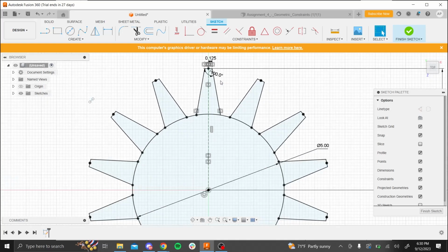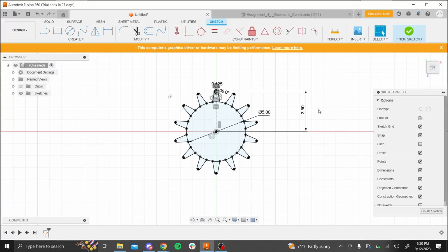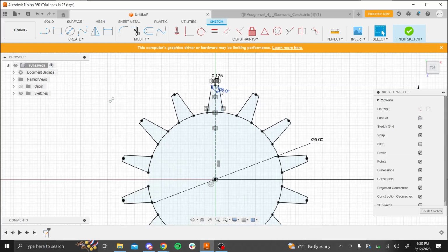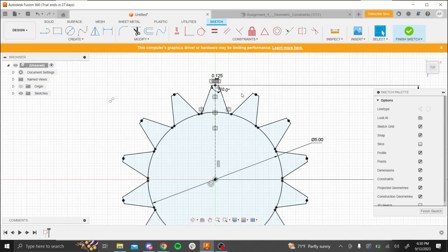And again, it's really nice because if you change any of the dimensions on the original profile, it'll change it for everything, right? So if I wanted this to be 3.5, it changes all of them, which is really, really helpful. Oops, that's too much. A lot of these things are here so you can edit your parts very easily later. If you're making individual simple parts, it may not seem like a big deal, but later when you make more complicated things, it becomes a big deal.